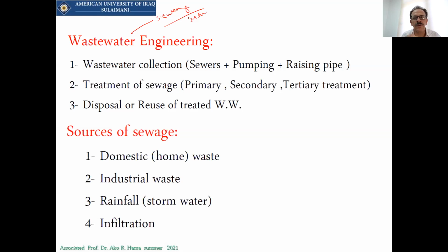Municipal means that household sewage is called sewage, while wastewater will be the municipal and maybe the industrial, maybe the commercial areas, maybe the stormwater. All of these together are called wastewater. So wastewater is a general term, and it refers to the whole activities, while sewage is just a specific case of wastewater, related to the municipal or household sewage.